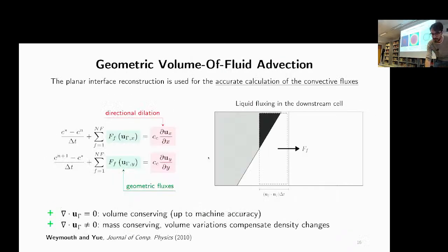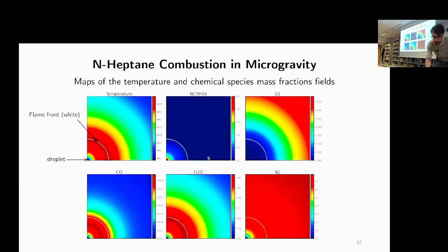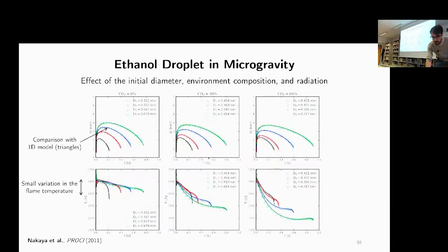And what you can see here is that by including this dissipation, we reduce the flame temperature, especially in these cases at high CO2, because the expression for that radiation is a direct function of the amount of CO2 in the environment. So this is the bulk phase gas radiation. Of course, because the optical thickness is small, we are not including the absorption of radiation at every point of the domain. It's not so easy to implement good radiation models, and so this simplified version works in these cases. It's fine for these cases.